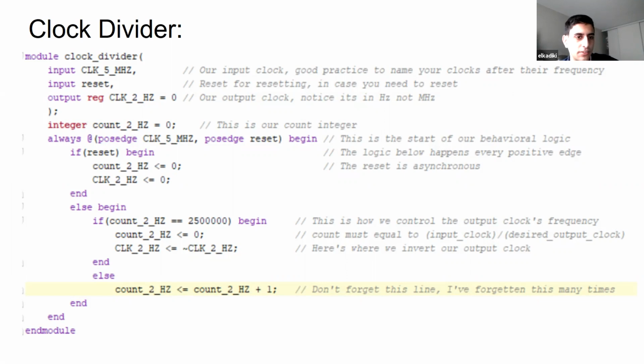It's usually good practice to make sure that your registers are all set to a value, initialized. Currently, when you power it on, they'll be in an unknown state until you hit the reset. This is kind of like a macro to say, hey, please clear these registers first. Don't just use whatever's in there.